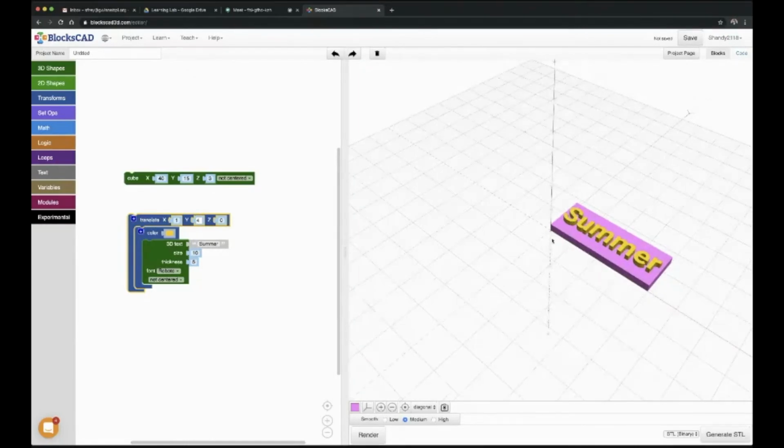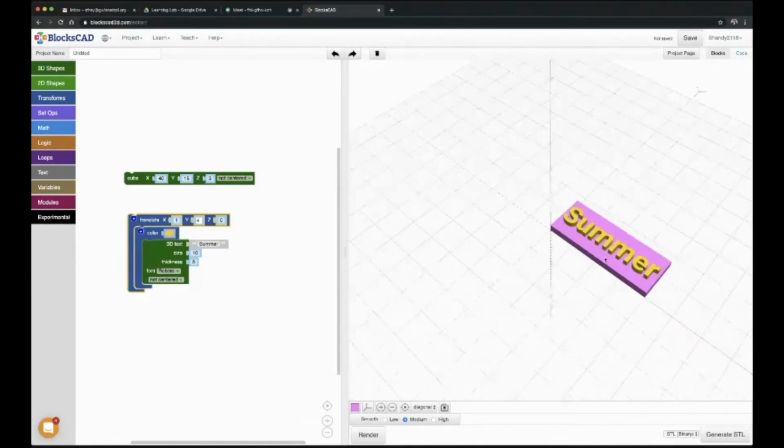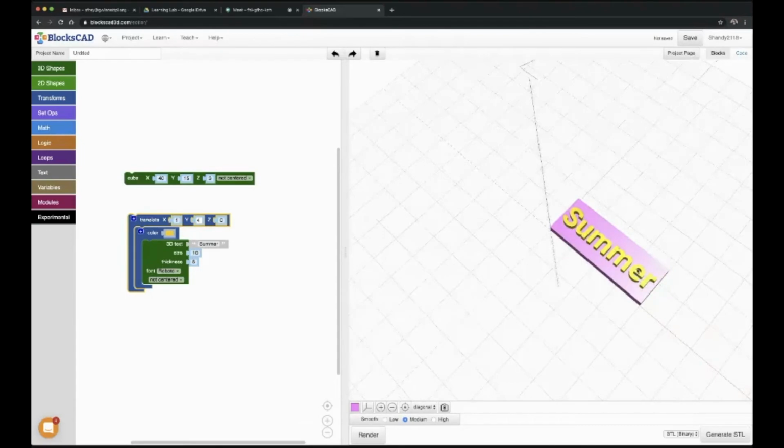So now that we have this, the first thing is, whenever you're 3D printing, if you have anything in the middle of something and it's not connected, like the little middle of this E here, and it's not directly connected to the block, it's going to get lost. And then you're just going to have a big empty E here without any information on the inside, basically.